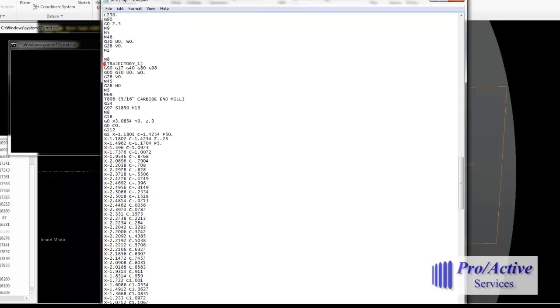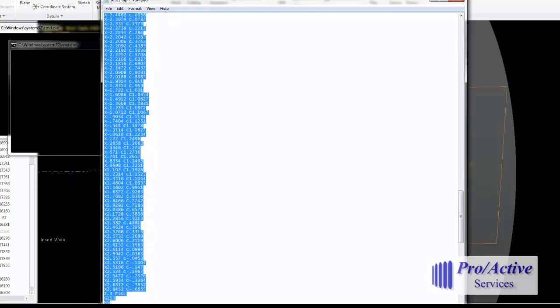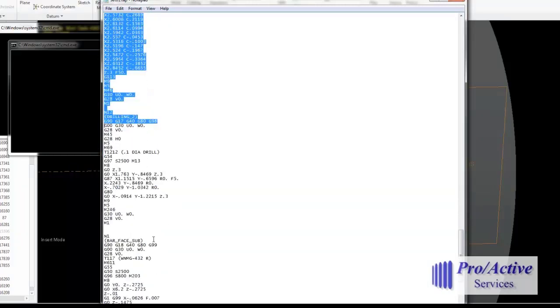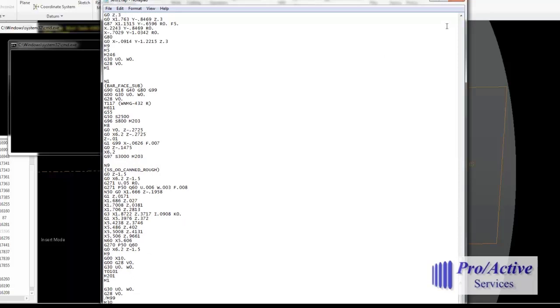This is where I machined around the cam surface, outputting a G112 cycle. The G112 cycle will position the tool in the upper X quadrant, and the milling motion will involve a lot of C rotations along with, in this case, some X moves. So you can see this format was automatically selected based on the type of sequence. This is exactly what I want. Then I continued by drilling the holes on that canted surface right here, and it outputs the proper format for that machine tool. So I'm happy with this program.